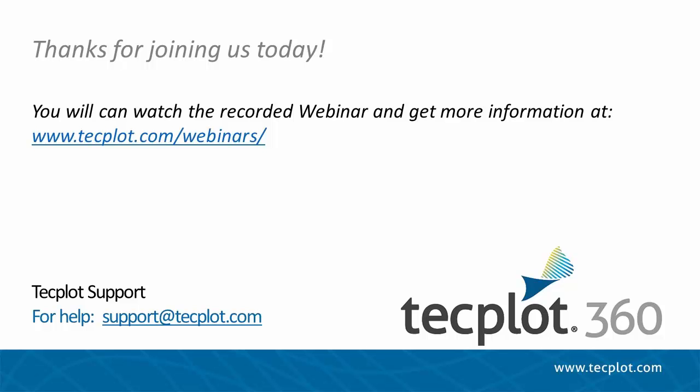Okay, let's do 2 more questions here, and then we'll call it. So, is the C library callable from MATLAB without the C compiler? The answer is yes. Now, Devin does have a compiler installed on this machine, but there's no reason that you need a C compiler installed to use this MATLAB capability, the call lib and load library functions. And then, is it possible to get a butterfly plot using Tecplot 360 synced with MATLAB? I have to admit, I'm not quite sure what you mean, so maybe we can follow up post-webinar.